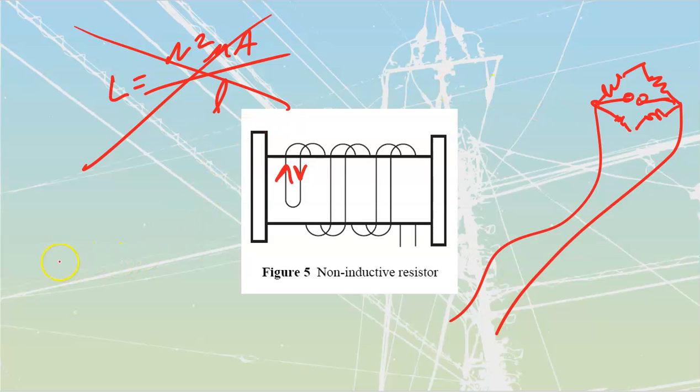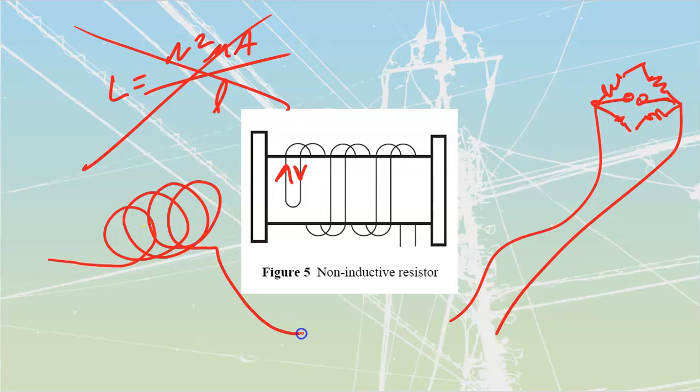What you'll see electricians who don't know what they're doing do is take them and wind them into a nice little coil, and stick a tie wrap around it. And then here's the load cell. It keeps it out of the way. Yes, it's neat, but electrically they have just formed this thing into an inductor.